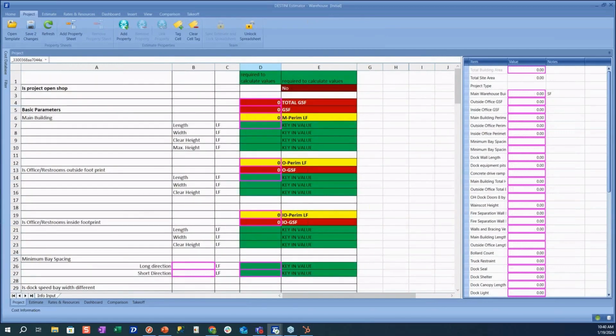So now for our project tab, we're using it to calculate the quantities of our line items. So we'll set up a questionnaire. We see those questionnaires be from really anything that could be 10 to 15 questions if we're thinking of an area study or a mixed use project at a very high level, or it can be more detailed as we have here, to where the user's prompted for approximately 50 to 60 questions as they're working their way through. As we've gone through and made entries to our project, now we've calculated gross square footage.